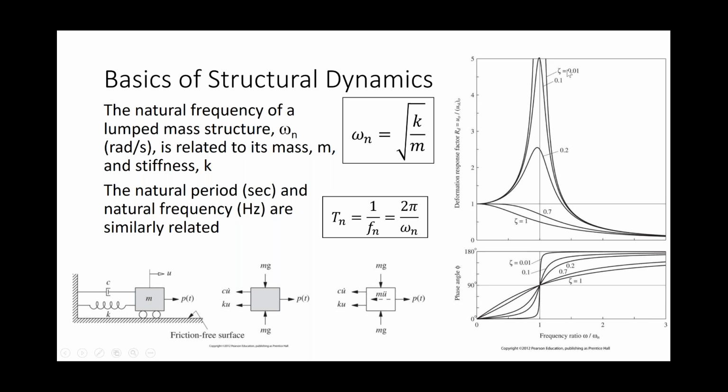That amplification is attenuated if you've got substantial damping on a structure. So one of the things you can learn, if you can measure the amplitude of oscillations due to a known forcing, is the damping of the structure.